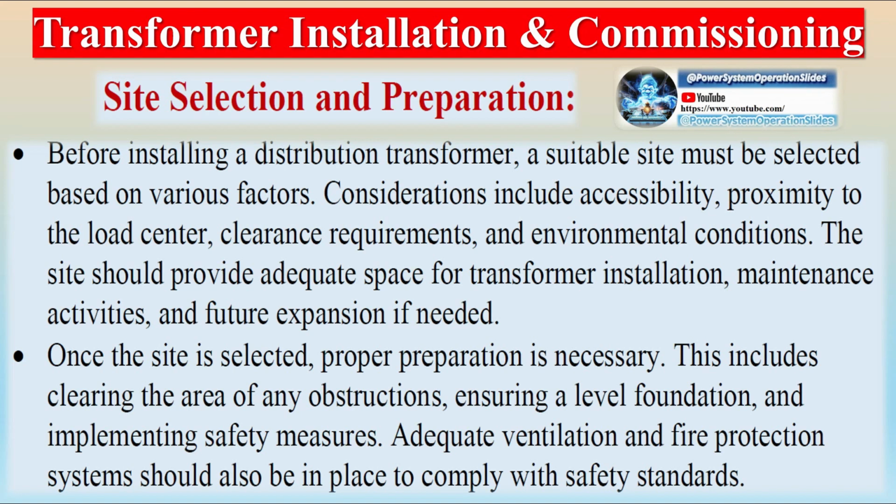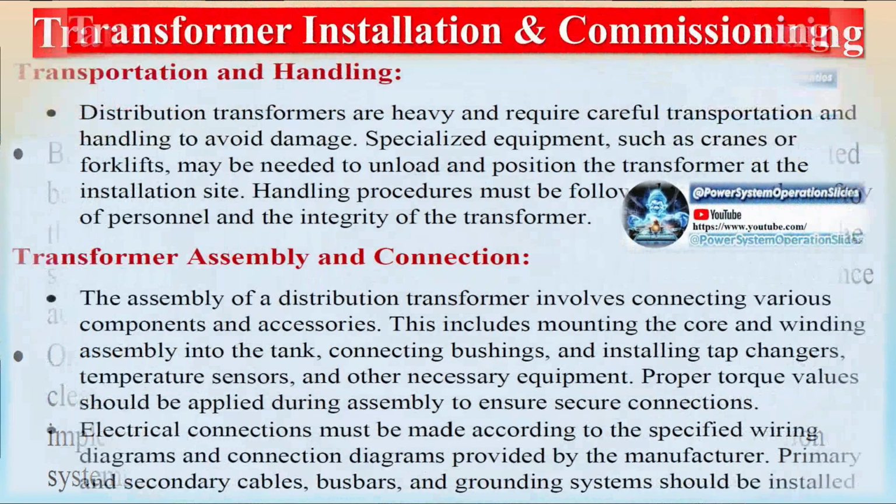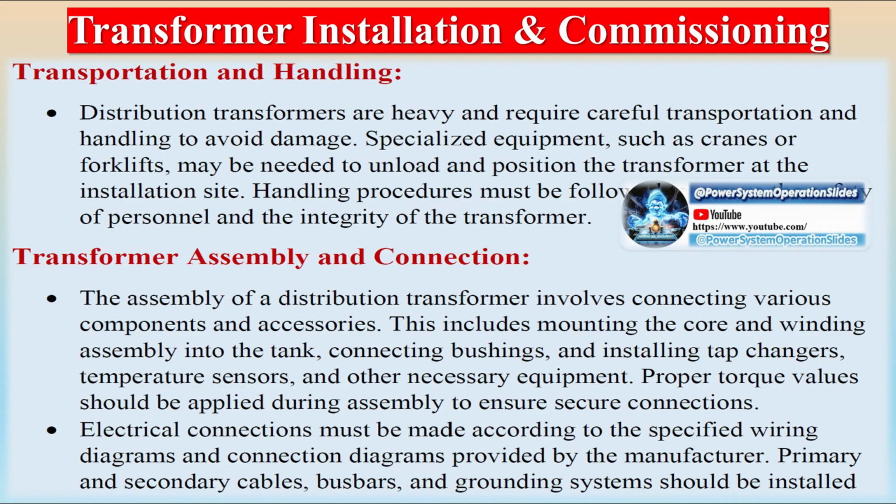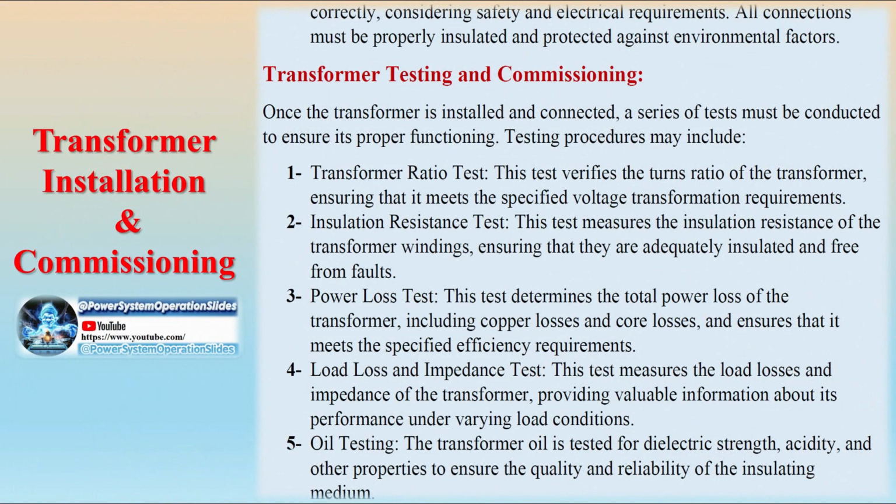Transformers are not perfectly efficient, and energy losses occur during operation. These losses include copper losses in the windings due to electrical resistance and core losses due to hysteresis and eddy currents. Transformers are designed to minimize these losses and improve overall efficiency.